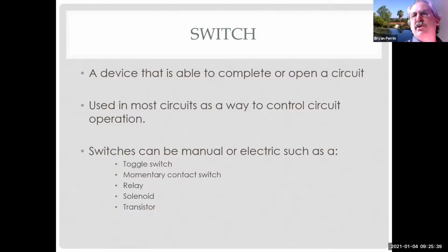That's why we use a higher voltage in the house. That's why we have 220 circuits, or I mean 240 or 480, when we start building bigger stuff, commercial stuff, because I can do more work using less amps, which means I don't need to run as big a wire.